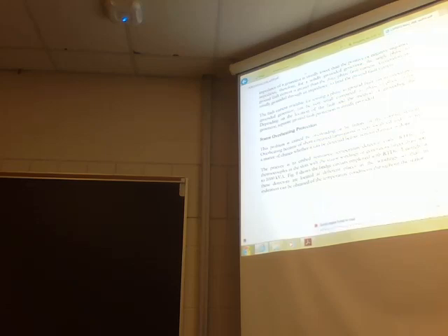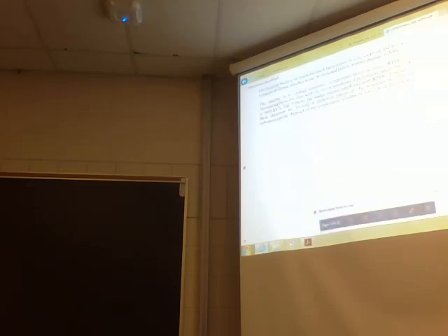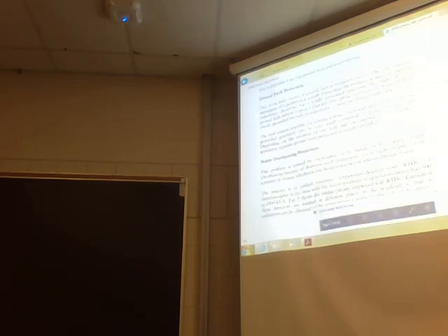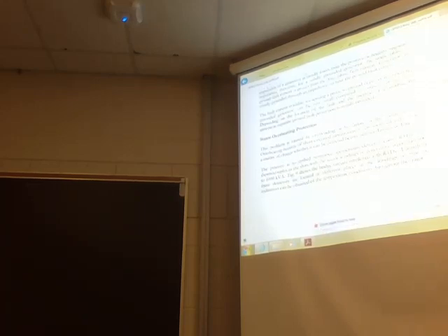So figure 9 shows the bridge circuits employed by the RTDs. Enough of the detectors are located at different places in the windings so that an indication can be obtained of the temperature conditions throughout the stator.